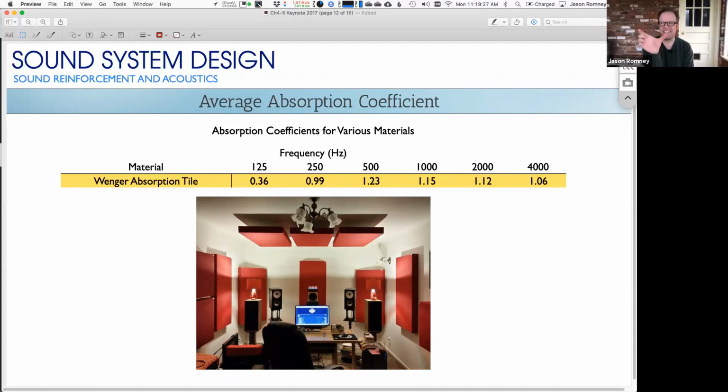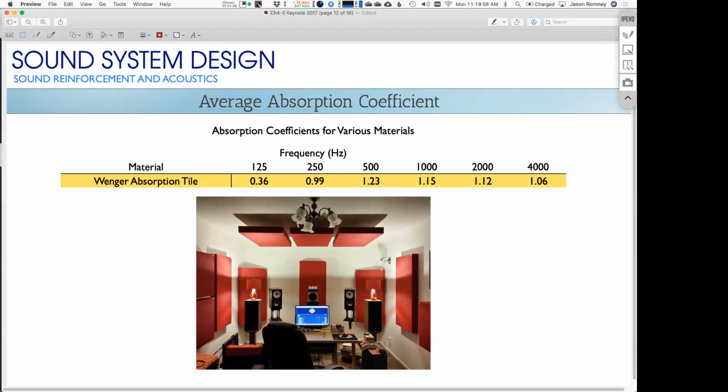So the tile is thick, right? That 4-inch thickness around it introduces new surface area that is absorptive into the room. And so you get to count that surface area against the surface area that got covered up. So you are actually covering that spot on the wall with an amount of absorptive surface area that is 123% of the area that got covered. Oh, because when you're including the sides, you're covering wall space that doesn't exist.